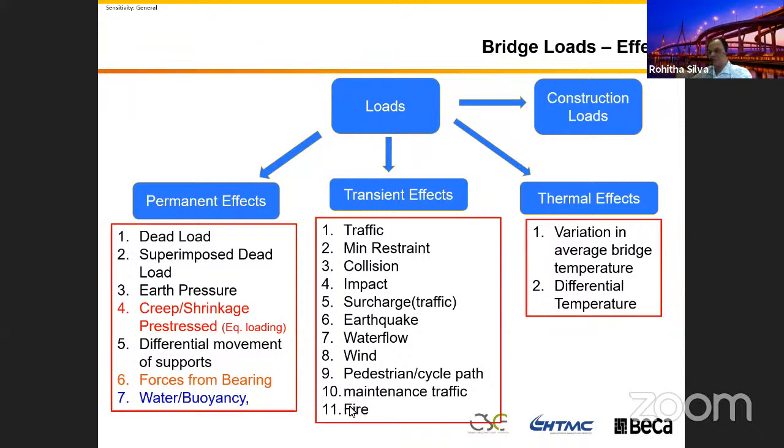And the fire loading also, for certain bridges, we need to look at the fire design as well. For example, you can have a bridge that is quite long, and underneath you let the traffic go, but if there is a tank or something that blew up underneath, if that bridge is quite long, let's say 300-400 meters, that heat might impact your bridge.